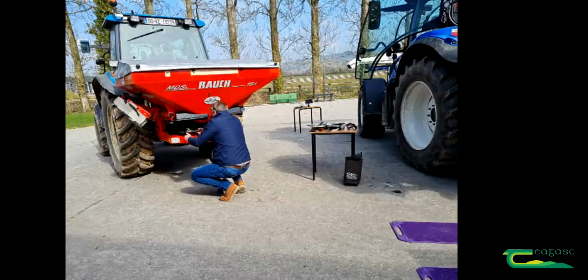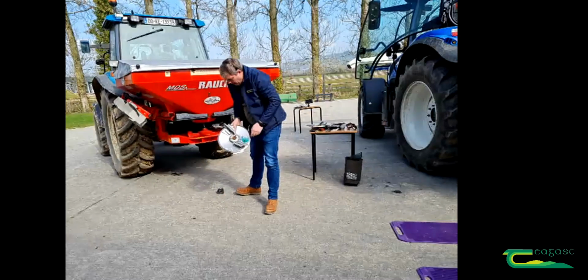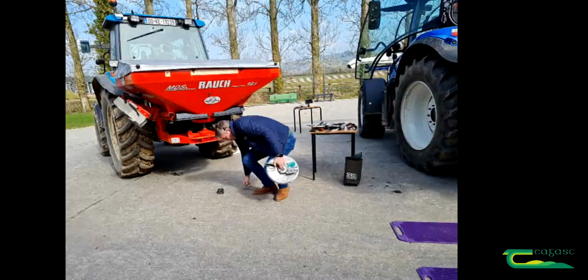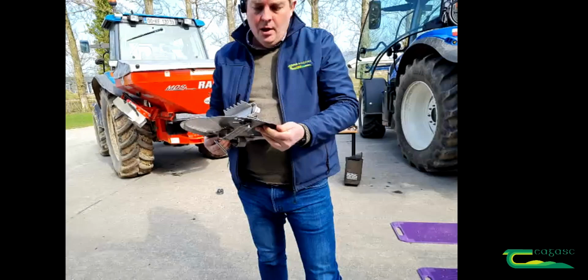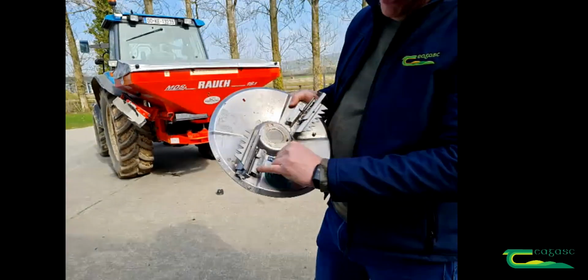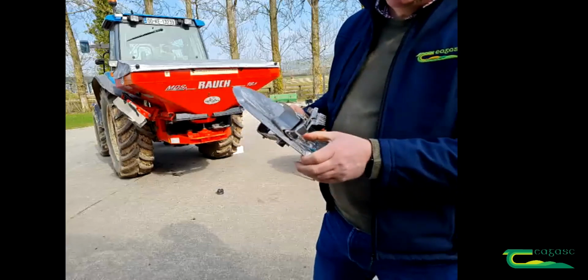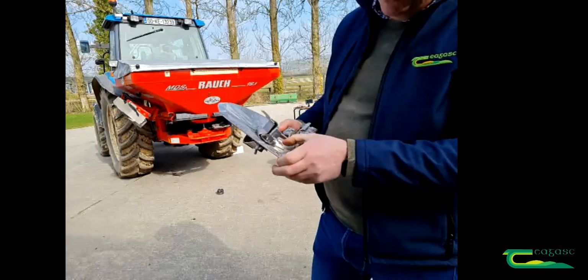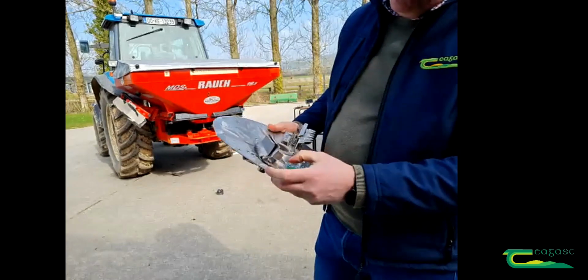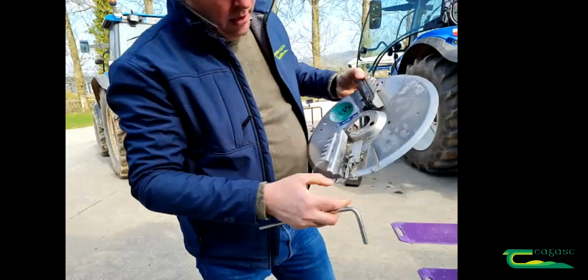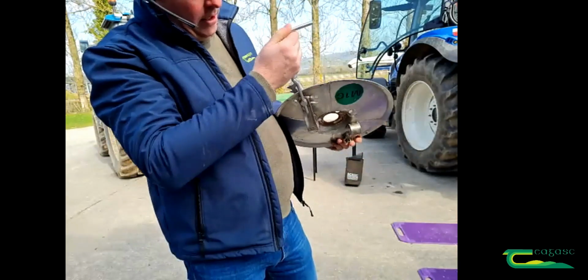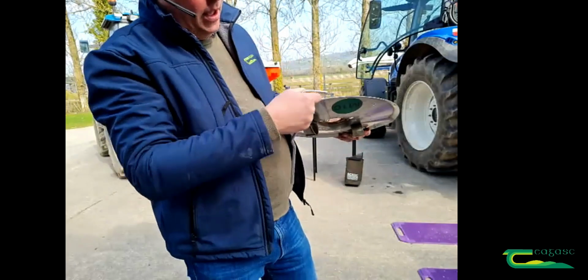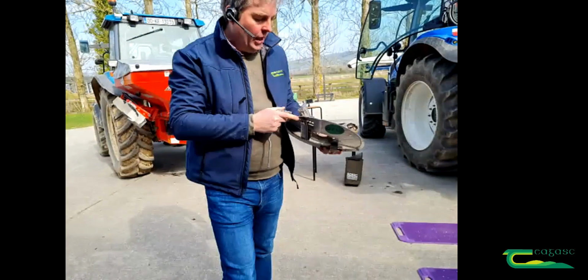So again, this will normally be a task that you can do without tools, because it's something that we do need to do quite regularly. So coming in here, I have letters here and numbers here. So it was giving us settings earlier on. Now in this case, this vane here is set to B2, okay, and the vane on this side is set to D3. So we can adjust that by putting this tool in here, pulling down the spring, and we can adjust our vane over and back, okay.